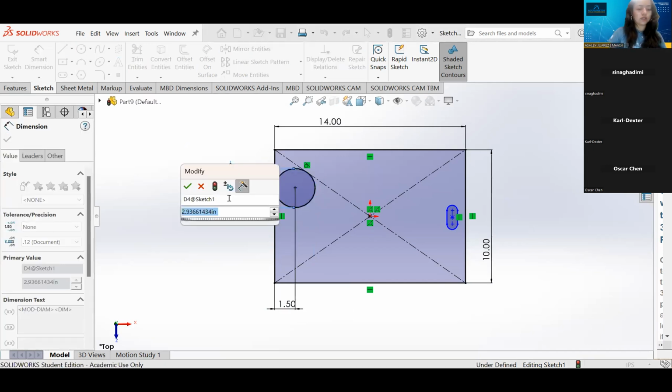This is 1.5 times 2. This is another thing I wanted to show. In your dimensions, you can make these things be equations, and SolidWorks will read that because technically when you add a dimension in, it's adding it as like a calculator, so to speak. So let's say, for example, you're adding segments of a part and you need to know how long it is together.